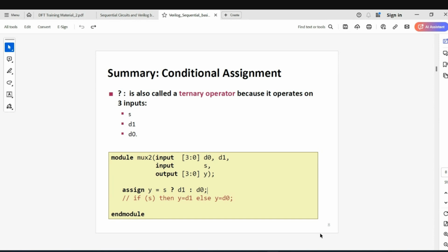Yes, sir. Can you explain that question mark once again, sir? Okay. So the select line is a user choice, which data has to be passed on to the output. The mux has this selectivity, which is a question mark, because you don't finalize here which one you want to select. You finalize it in the test bench.